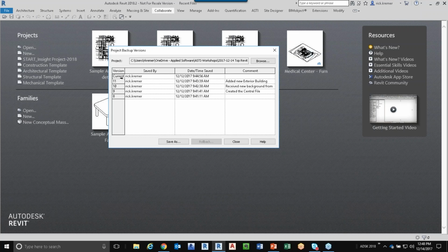My recommendation is at this point, the project manager then makes sure that everyone on each one of your computers deletes your local files. It's critical that you delete those local files because you do not want to have a local file that still has that corruption. So again, it's super critical that you delete the local files on the individual workstations.